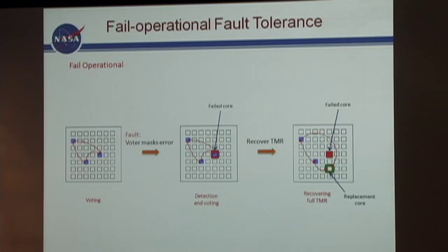Now, a slightly more complicated example in this system is when we're interested in robustness, and one way of achieving that is to use redundancy. And of course, one of the most well-known techniques of that is triple modular redundancy, where you take 3 computations and you vote them, and at least 2 need to agree in order to come up with a result.